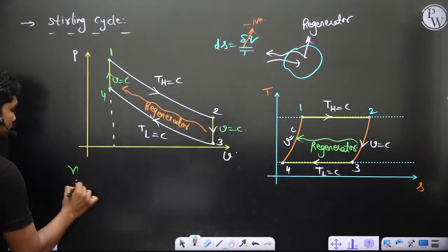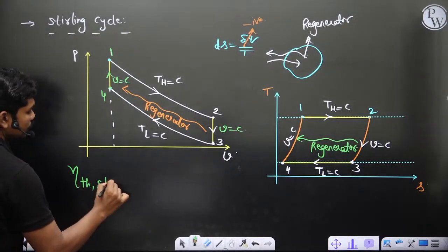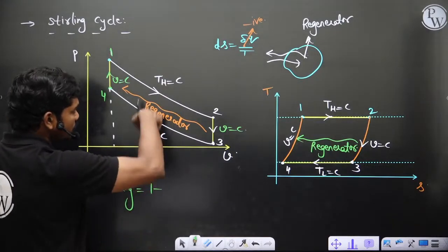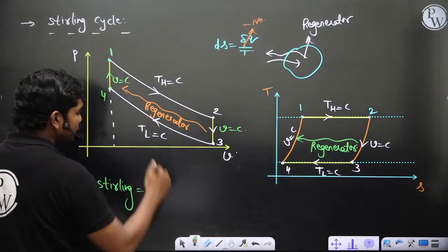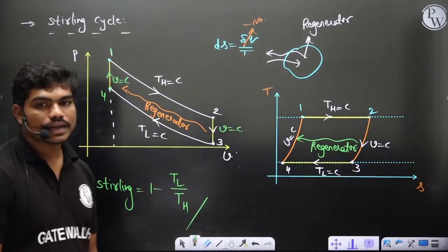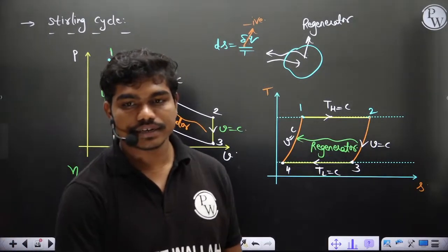And clearly if you try to calculate the thermal efficiency of Stirling, you will find out it is as per Carnot's cycle. Heat additions are isothermal and temperature limits are the same, TL, TH. So efficiency should be the same as Carnot efficiency. So this is what you will get. Same as Otto cycle but with isothermal heat processes.